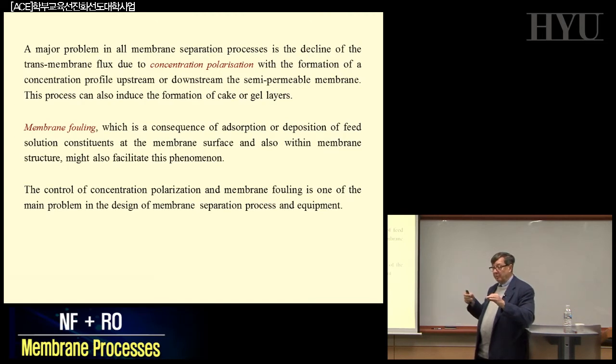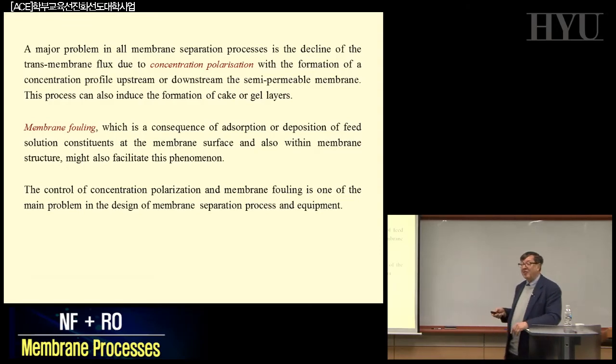So in principle, if you change temperature, you are changing the transport parameters which are present in the proportionality between driving force and flux. So you have to take care of this. But this does not affect the driving force of the system too much. In membrane distillation, you will see that we don't have any significant effect from concentration polarization, but a dramatic effect from temperature polarization. In this case, it was just the opposite.